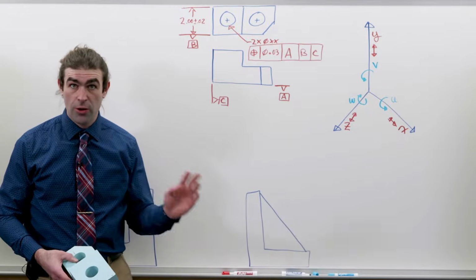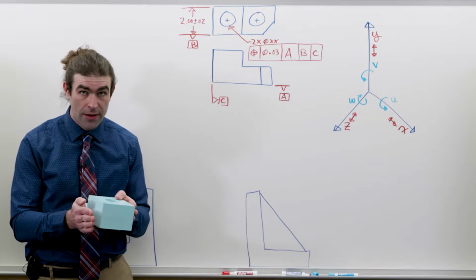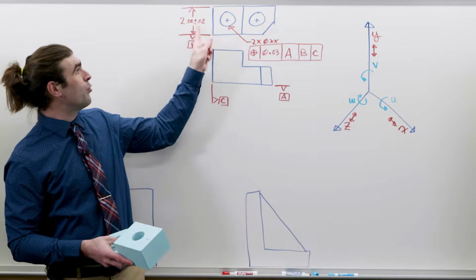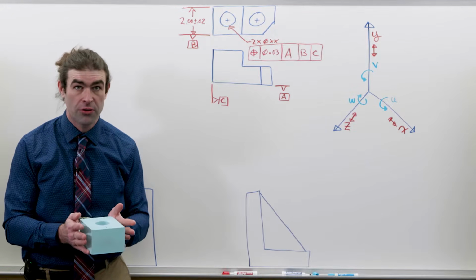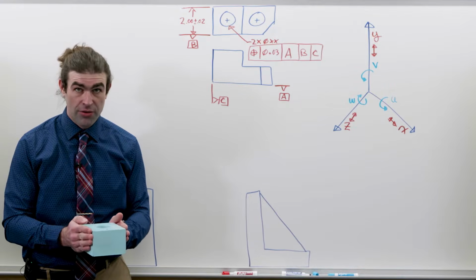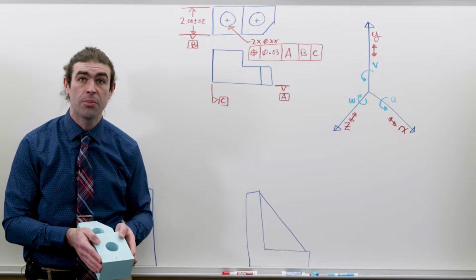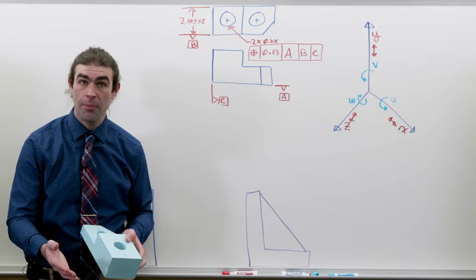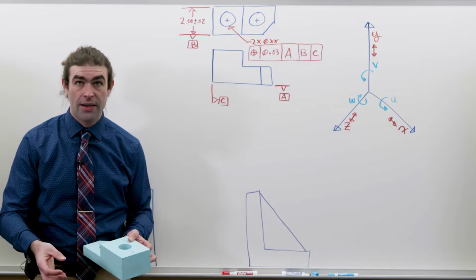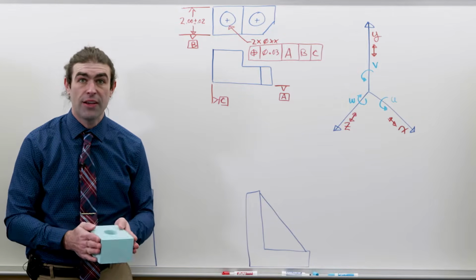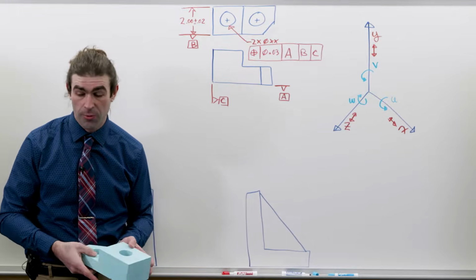That way, when you go to inspect it, you don't need that expensive centering vise. You could just set two angle plates 2.02 inches away, so the MMC of that feature or the virtual condition if it applies, and then measure from the center of those two angle plates. The part could move around between them. Okay? It's a little bit more complicated to set up, but what it allows you to do is have something like a robot check parts for you, because now you have fixed gauging. You don't have to center the vise and then find the middle. Okay?